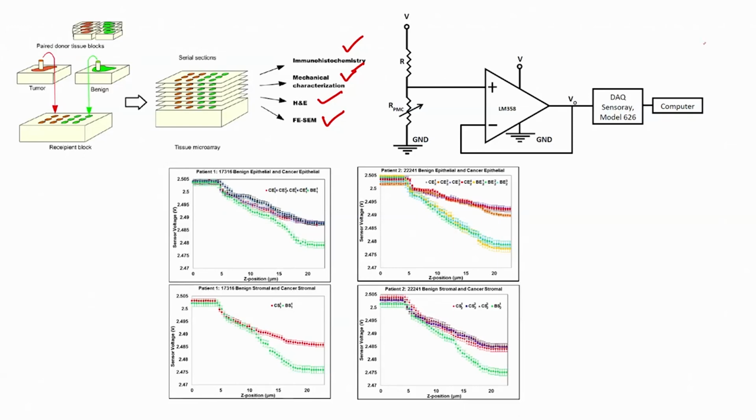Alright. This is a simple electronic module that we can use, where your piezoresistive microcantilever is given by PMC. It is connected in a voltage divider fashion, which you can see right over here. So, if the voltage is plus 5 volt, my output here would be 2.5 volts. That 2.5 volts I am applying to LM358, followed by a sensor that finally shows the display on my system, right. This is just one method. There can be multiple methods to use a signal conditioning circuit along with a sensor.